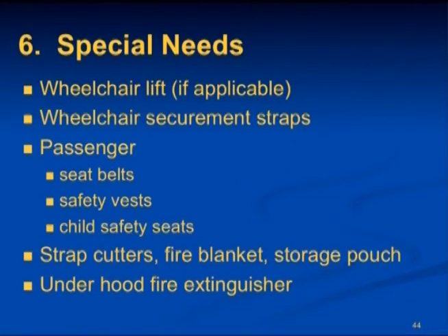Make sure you have a strap cutter. There should be at least 2 cutters on board and located in a designated spot easily accessible to the driver but out of reach of the children. There should be a fire blanket stored in a storage pouch, and there should be an underhood fire extinguisher in good condition in the newer buses.